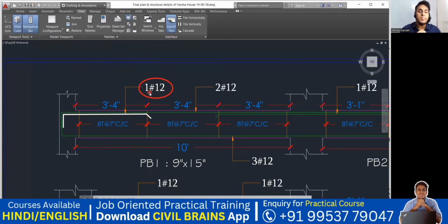Okay. So that means practically what will happen here, the negative bending moment will be more. Because of that, more moment will come. Because of that, more steel is required. So this bar is again needed. So practically how this will look now, I'll show you. Let me draw a small view for you. I'm drawing a front view. Okay.